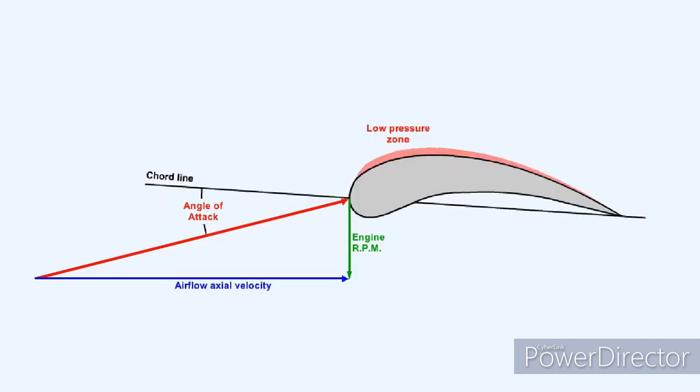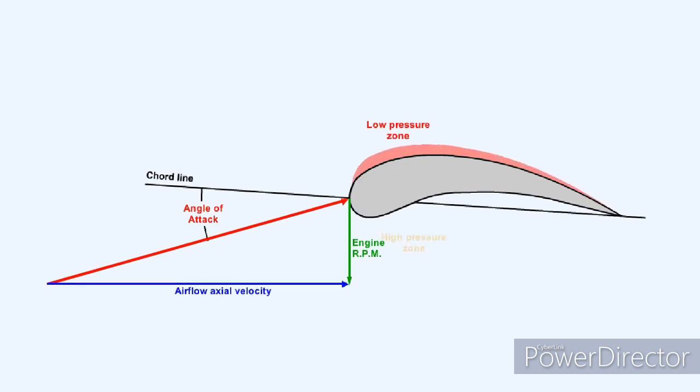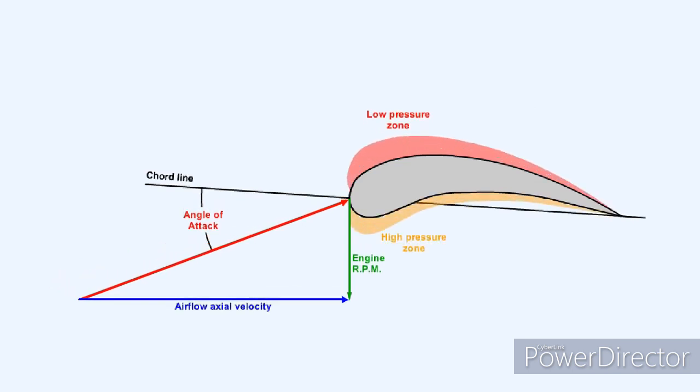This will have the effect of bringing the axial velocity of the air in the earlier stages of the compressor closer to the optimum value, and also of reducing the choking effect in the rear of the compressor.